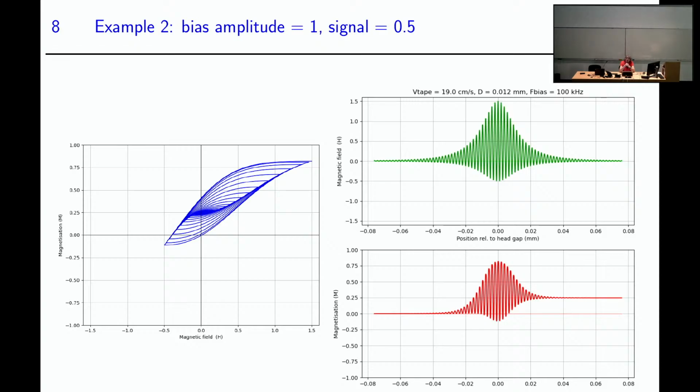Okay, so 4 times oversampling, do you think is enough for this application? For what I do, yes. Because I don't model the bias signal directly. I just model its effects. So then something which is a lot higher than the audio range should be enough.